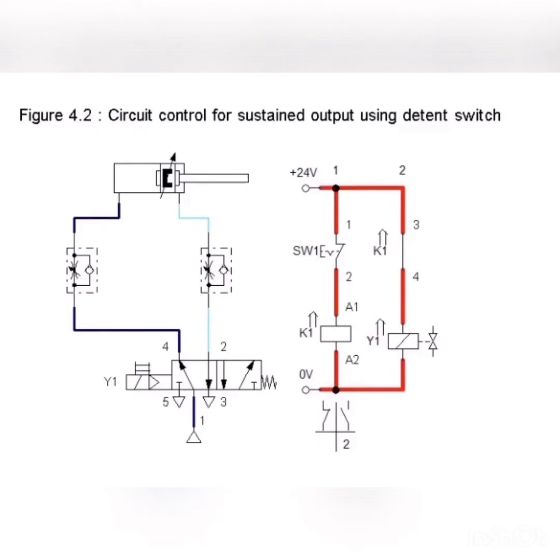This switch is also known as a latching switch. When this switch is pressed, the block of the valve will change from right to the left block and this will make the airflow go through the valve and straight to the cylinder. This action makes the cylinder position change to extended and active A+.